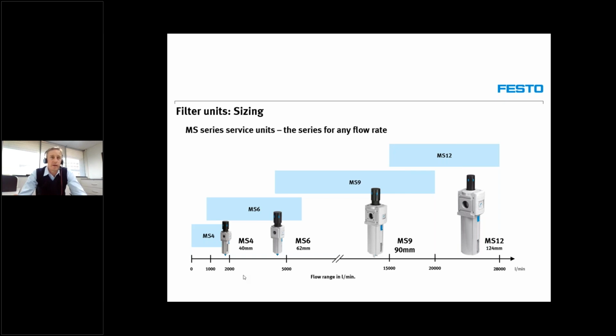But as you mentioned, it might be a situation that you don't have enough air supply. So even if you've got a big diameter tubing going to the actuator, it doesn't necessarily mean that you've got enough air supply to that. So that might be a problem, especially if you run over large distances. Thank you. I think if I can interject there, Hannes, I think the rule of thumb is exactly like you describe. If you try and size your air supply according to port size of the actuator itself, that's really the governing factor as a rule of thumb.